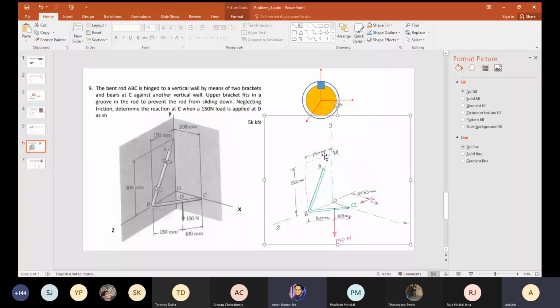No. It was not possible if you have two rings. If you only look at one at a time, all three rotations are possible. Yes, sir. But here also we can see two rings. So in this also, if I only look at the lower bracket, then two translations are restricted. If I look at the upper bracket, three translations are restricted. Individually, they are not restricting any rotation.